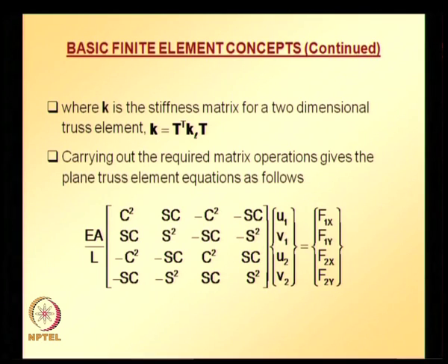So that is why we need to first compute the local element deformations, and then using shape function for axial deformation element we can calculate strains, and then from strains we can calculate stresses, and then from stresses we can calculate the axial forces, elemental axial forces.